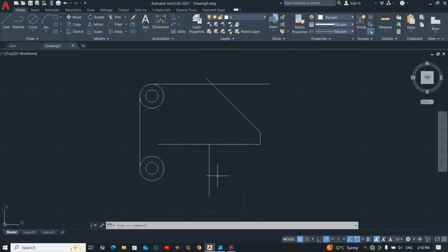So what we are going to do is, let me delete this line. I'll take a straight line. I'll just draw a straight line here. Now you see, press on your tab key, enter an angle of 45. You see, it's going to be inclined to this line. Now if you use the normal tangent here, you get it wrong. So this is the best way to do it.